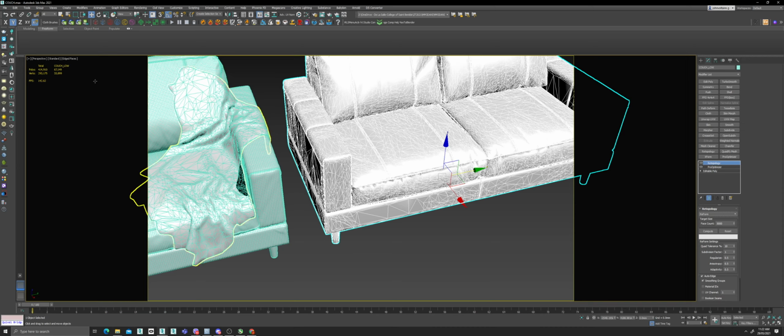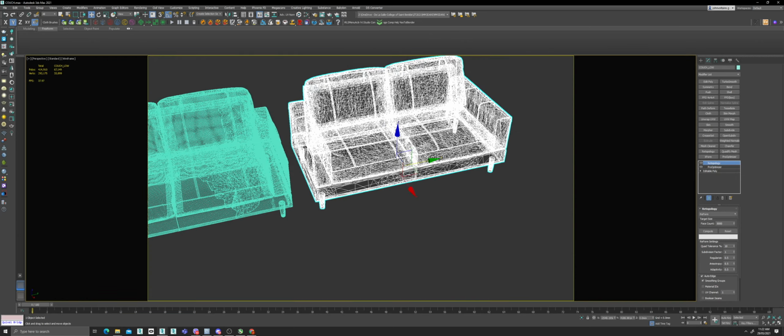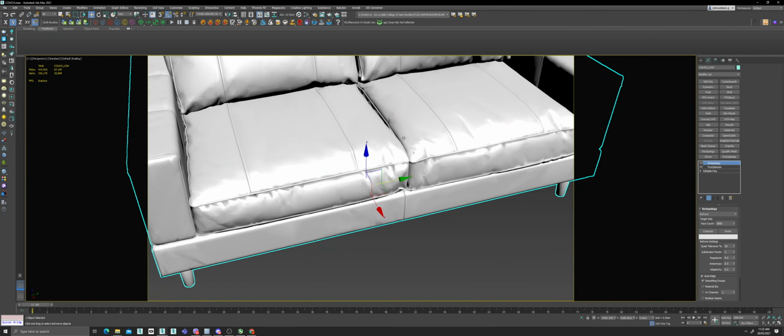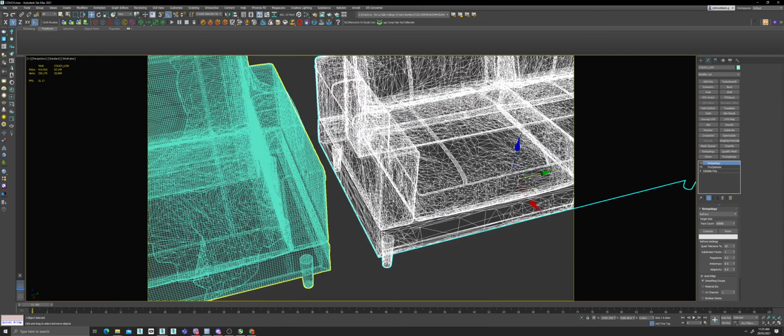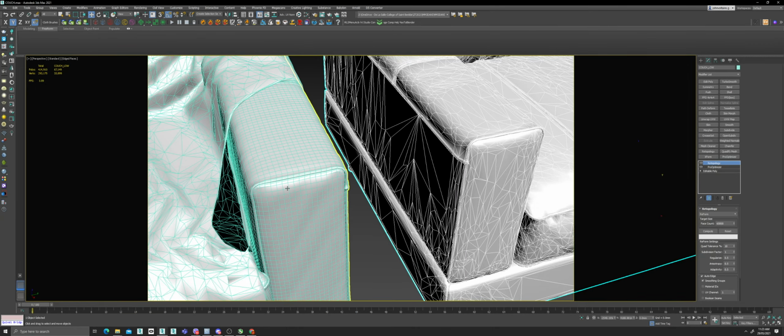With your statistics, it says here you have 33,000 or 34,000 vertices with this amount of detail retained. That means we can use that number here in this face count. Face count natin is 67,000 faces. Polys. Hindi vertex sinasabi, so faces. So we're going to use around 65,000 faces. And then regularize to make your edges regularly spaced, just like this.